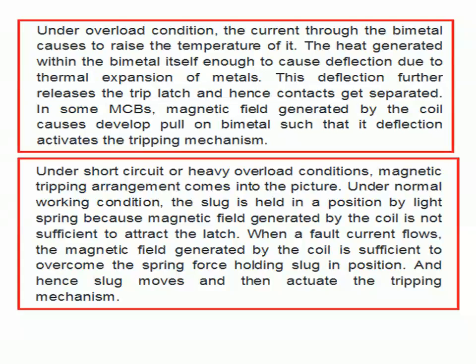So the second one, development of magnetic circuit. The magnetic field is not able to overcome the spring action. Magnetic field is weaker when normal current flows. When the short circuit current or fault current flows, the magnetic field developed is sufficient to overcome the spring action.